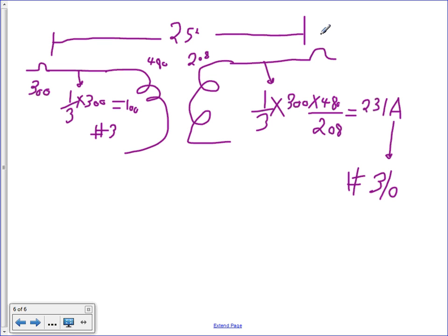And what size overcurrent protection device can I use here? You guys got 3/0? How much? 225? 225. 250. Then you can go as high. Yeah, you go by the conductor size. The largest that you can put here is 250. You don't have to go 250. The largest that you can go is 250 or less, because you go by the size of the conductor.